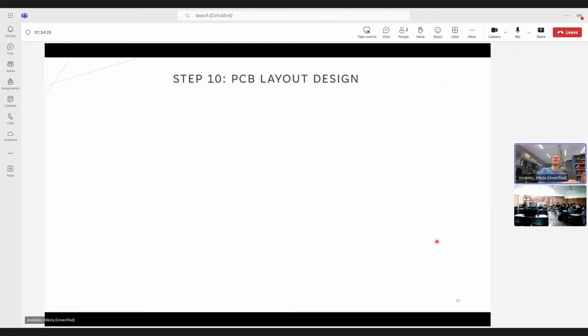We saw where the analog front end needs to go, where the, for example, digital part needs to go, and so on. So you need to, in a wise manner, organize that. You need to separate these domains. You need to decouple these domains. That's extremely important. Many engineers, actually, even with, let's say, long and big experience, sometimes fail to do that properly.